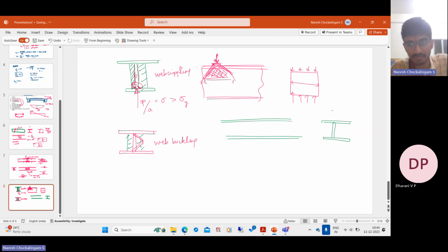Along the length, the web is very long, so it will buckle along its weak axis. This is the weak axis. Now, what a stiffener does is it places a member like this. You can call the width of the stiffener BS. It looks like this in the side view. You provide a member to strengthen the web.